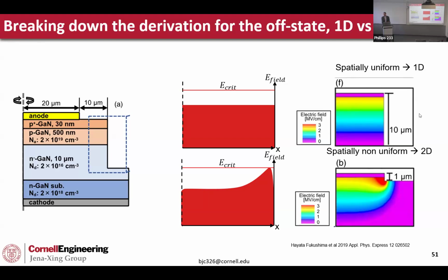In this case, they only wanted a 1D profile near the anode, because the ideal case is you just have a perfect cylinder of material and then there's no spreading whatsoever, minus, of course, states on the surface. If you think about the depletion width that they see at their doping, it's less than 10 microns at this specific point.